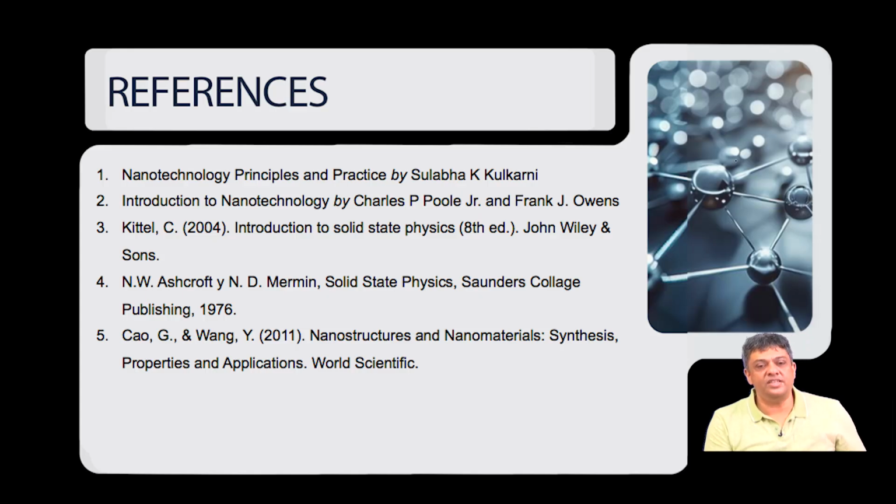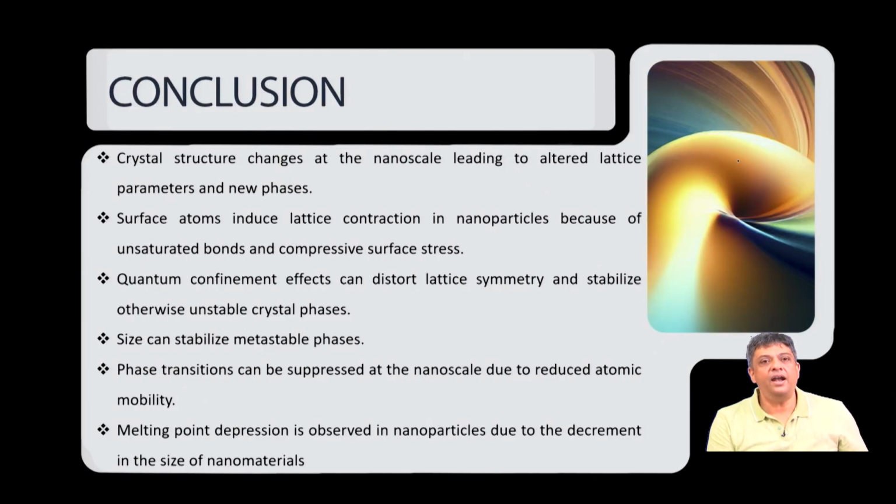You can use these references for understanding more about this topic, and I hope in today's lecture you could understand how the crystal structure changes as a function of size reduction, and size reduction can have serious impact on the properties of the material, and we took some examples today like stress, strain, melting point or dielectric constant.